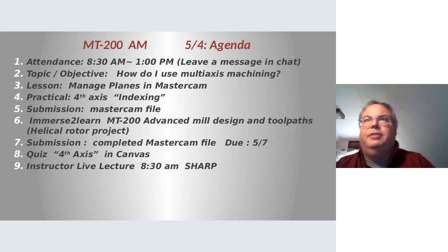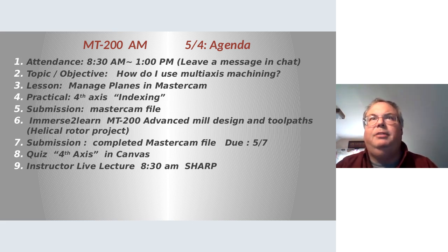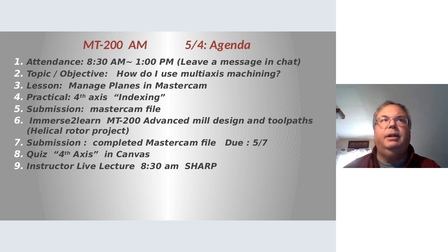Okay, so today's lesson will be on managing planes in Mastercam, and as I was saying, by setting up individual planes that represent our indexes and our movements of the axis in Mastercam, we'll be able to verify this, and it'll look just like it's going to look in the machine. So that's critical for troubleshooting any tool paths, so that we can check for collisions or anything along those lines.